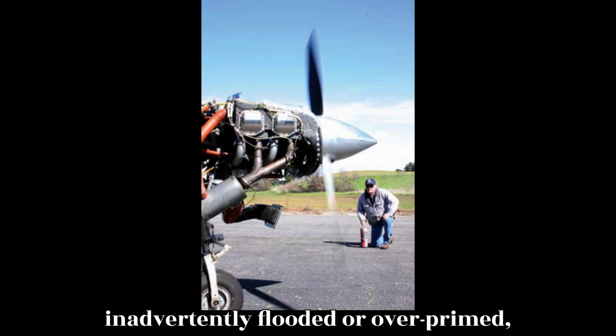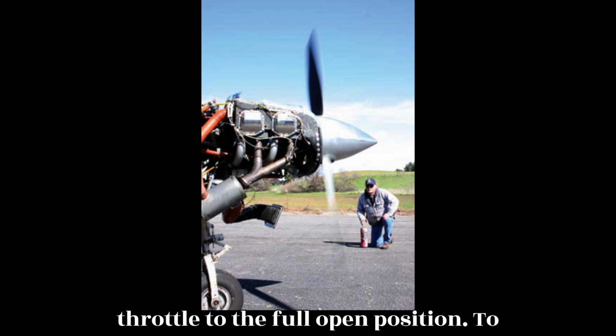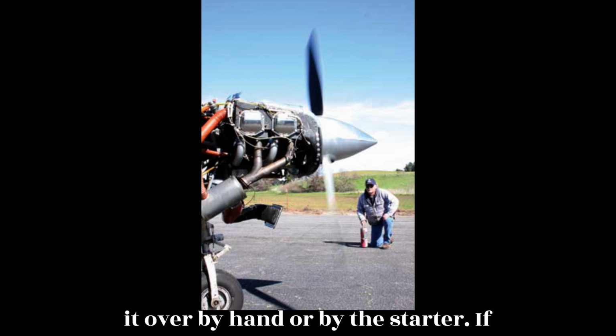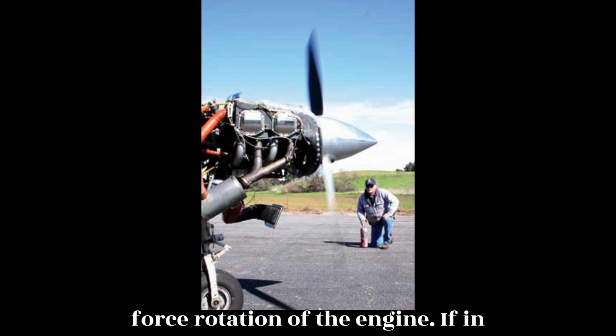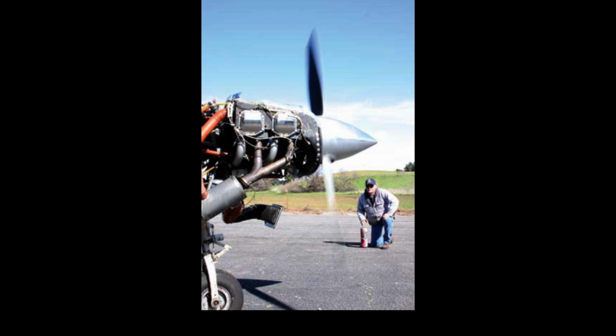If the engine is inadvertently flooded or over-primed, turn the ignition switch off and move the throttle to the full open position. To rid the engine of the excess fuel, turn it over by hand or by the starter. If excessive force is needed to turn over the engine, stop immediately. Do not force rotation of the engine. If in doubt, remove the lower cylinder spark plugs.